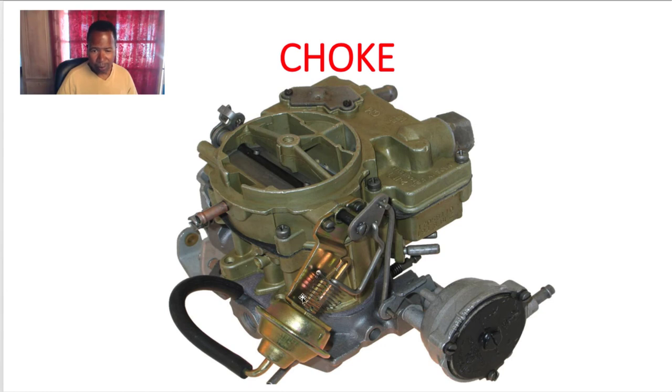Now, once you turn the key and start it up, this choke pull-off right here comes into play. You see this lever right here? It's hooked up to the shaft that hooks up to the choke. This choke pull-off works off manifold vacuum. So when it starts, manifold vacuum is going to pull on this diaphragm inside here. It's going to pull this lever and partially open this choke, probably 1/4 of an inch. If it doesn't, you're going to have a cold start problem or a start and dying problem. And a customer might complain it only does it when it's cold.